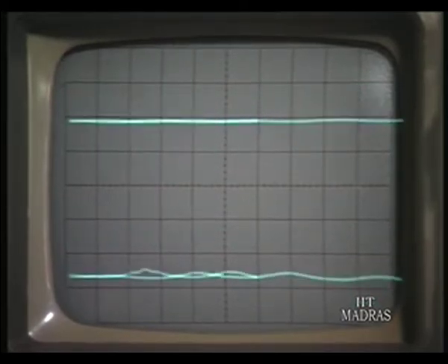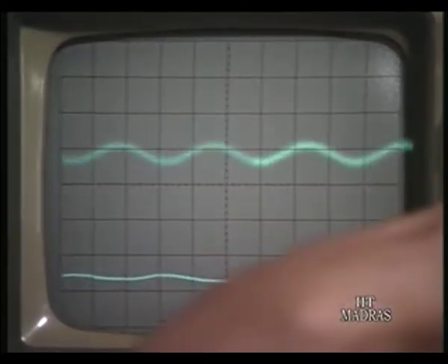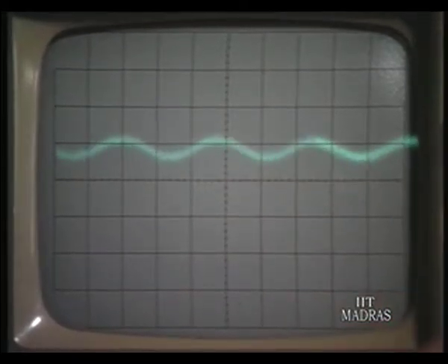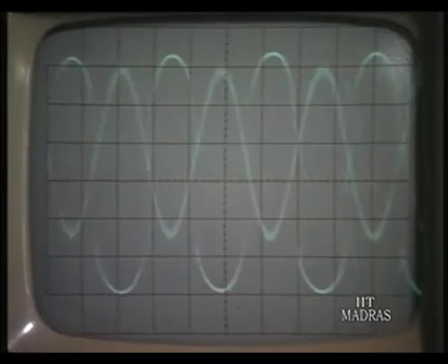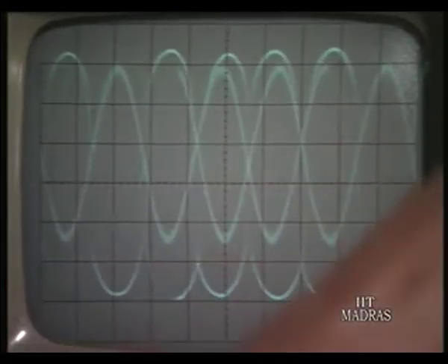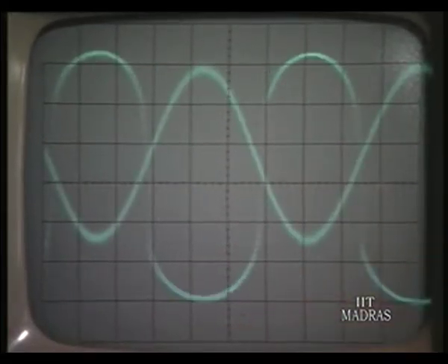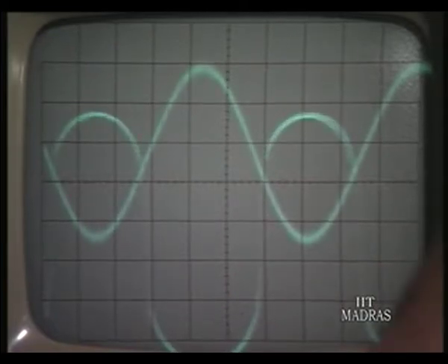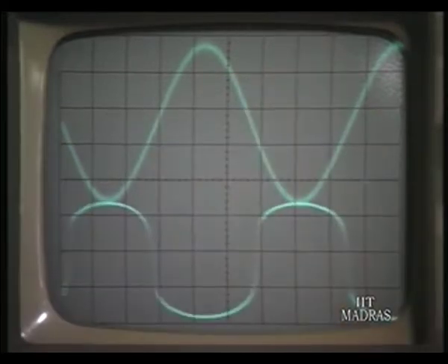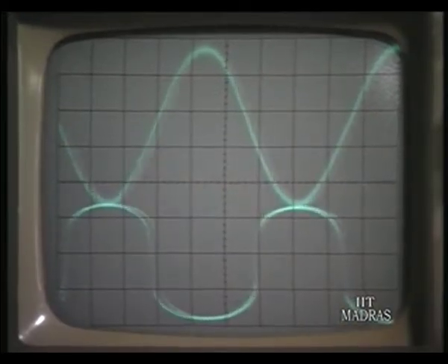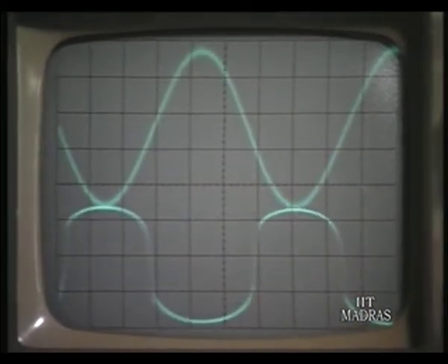Go to the higher range, and slightly right. You can see here clearly the input is very low and the output of the op amp is almost looking like a square wave, whereas the diode is still rectifying. Half wave rectifier output, please show.